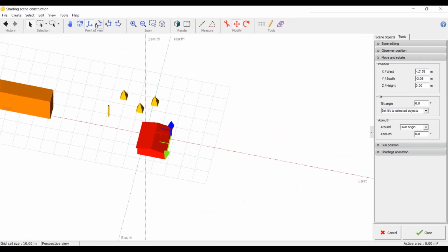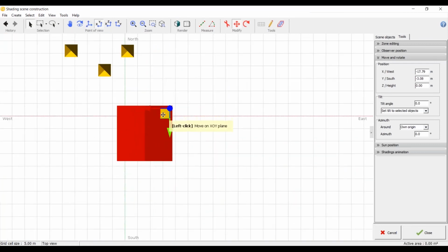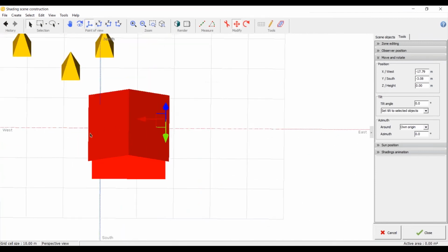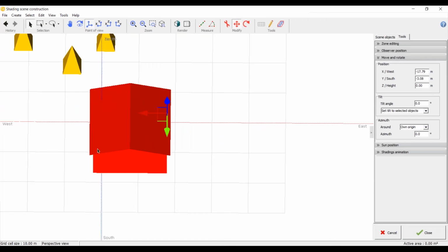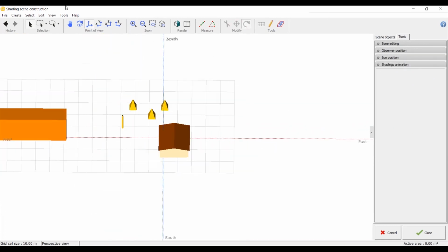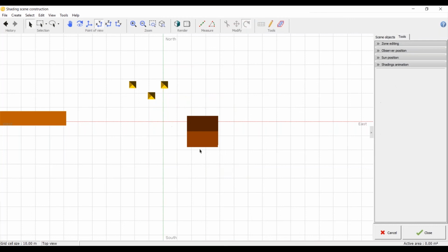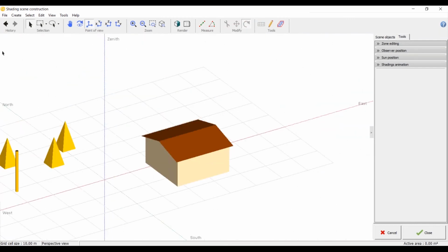And you can see, let's say I don't want my house to look like this. I might want the house to look more south facing. In this one, one section of the roof is facing east, the other section is facing west. But I'm going to put solar only on one roof, and this one is going to face south. So I'm going to click on the rotate option here, click on this, and then rotate my house. This is my house here.